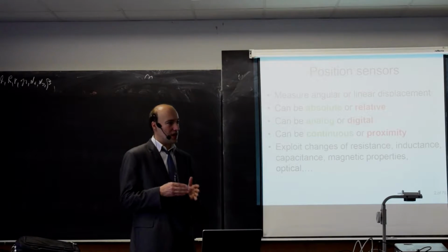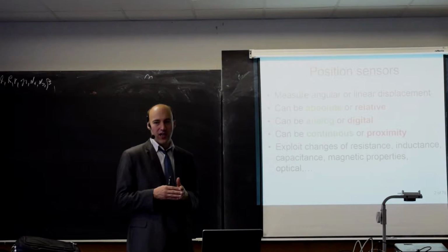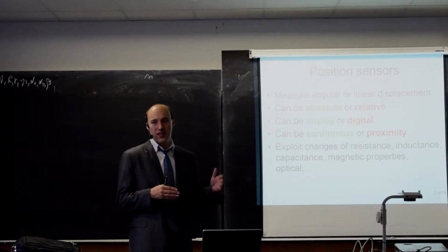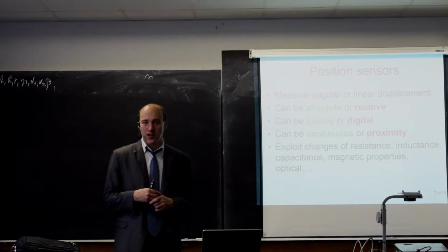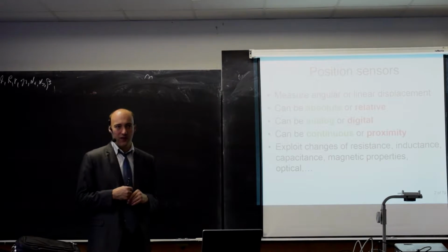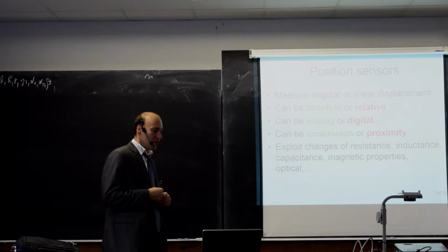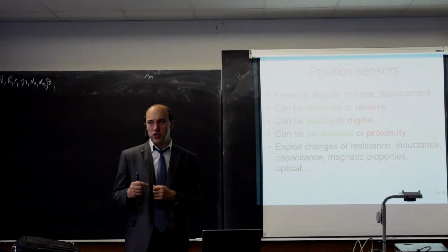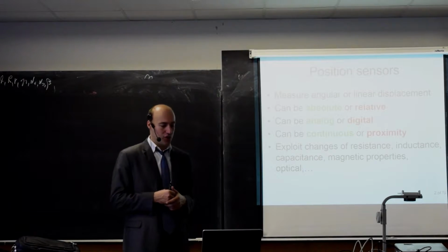So if you start at an arbitrary position, you can just say the motion was 100,000 pulses in this direction or in the other direction. And you know how much is a single step in the relative sensor. So relative sensors require this reference motion. They require end switches at some defined positions.